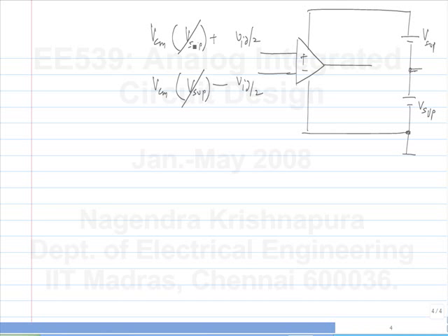The reason I am going through all this is what we will be designing will be single supply. What we use most of the time in a CMOS IC is a single supply. We will not use dual supplies because the single supply already is down to 1.8 volts. It doesn't make any sense to start with 2.9 volt supplies and work with that. So generally when you design ICs, you refer everything to a single supply. But the difference between single supply and dual supply is only with the location of the ground. Any op amp, even the ones that you buy off the market, can be operated with a single supply, or a dual supply. You just have to bias the input appropriately.